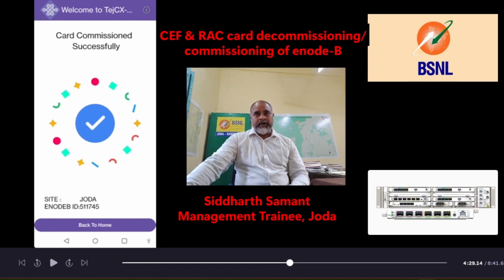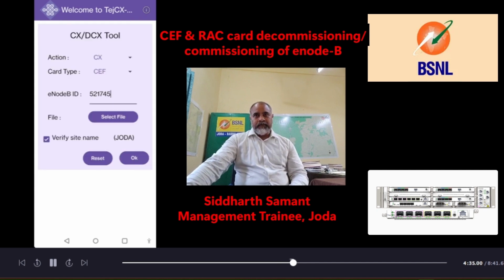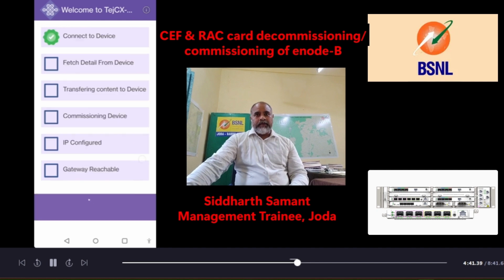After the successful commissioning, you will get this type of pop-up on your mobile. That means your rack card is successfully commissioned. Now we will go to the other rack cards. Here I am doing the commissioning of the CEF card. I have skipped all the other cards as the process is the same.